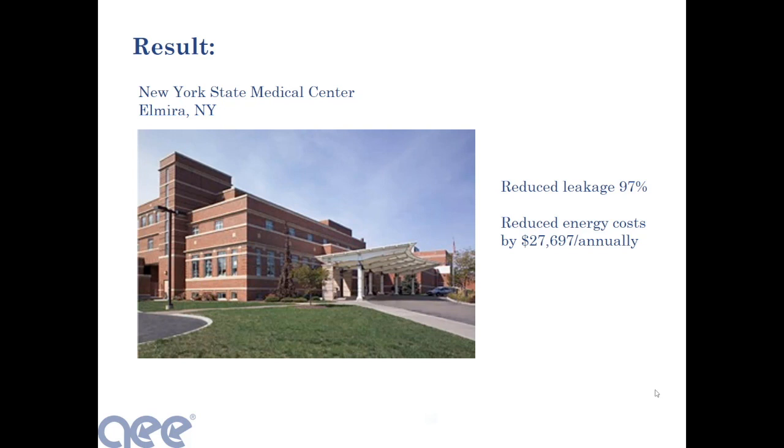Yes, sir. Is there an increase in pressure drop in the duct systems after this application? Great question. What does this do to my static pressure drop in my ducts? Well, since it doesn't coat the ductwork, it only sticks in the holes, there's no difference in pressure drop in your ductwork. Good question. Yes, sir. Does it work both with rigid and flex duct systems? Good. Yeah, what does it work on? This stuff sticks on everything. It's chewing gum.